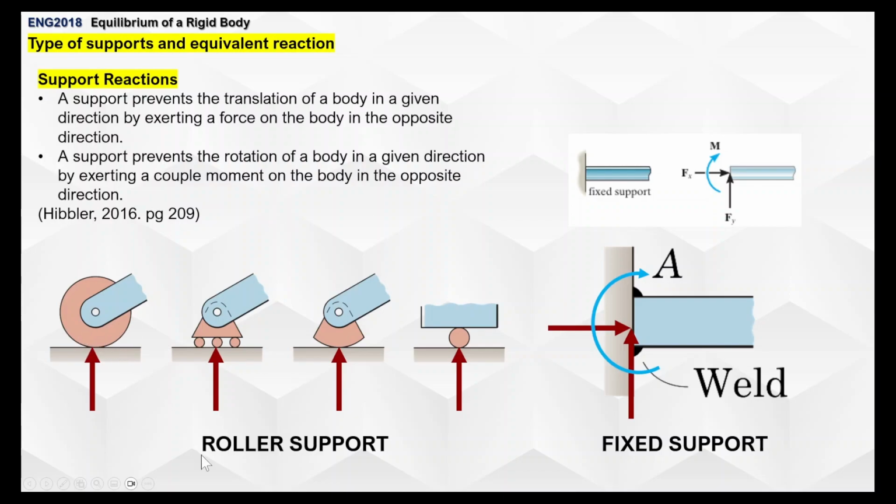Sometimes with supports, you've seen this problem or you've seen this drawn. These are types of roller supports. This is a roller support. They just look different, but they still work the same. This means that horizontal movement is allowed, but the movement it's trying to prevent is going down further. There's also the fixed support, and normally they're welded, sometimes fastened by a flange, so with a bolted nut, then a flange.